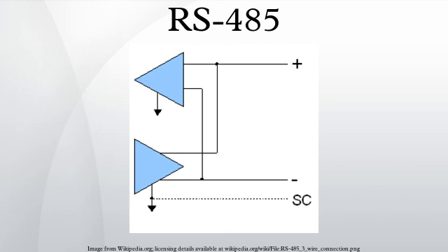Master-slave arrangement. Often in a master-slave arrangement, where one device dubbed the master initiates all communication activity, the master device itself provides the bias and not the slave devices. In this configuration, the master device is typically centrally located along the set of RS-485 wires, so it would be the two slave devices located at the physical ends of the wires that would provide the termination.